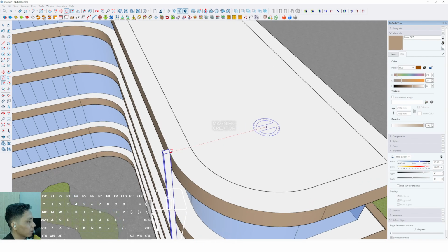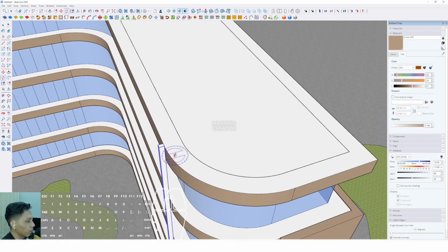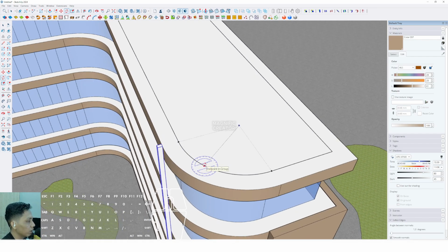Then we can press Ctrl on our keyboard, click from this object and place to this object, and then we can type 30 slash and enter. I'm sorry, it's too much. We have to repeat it again. We can rotate, select the position on the curve, click this one and place it to this position, and then we can type 15 slash and enter.